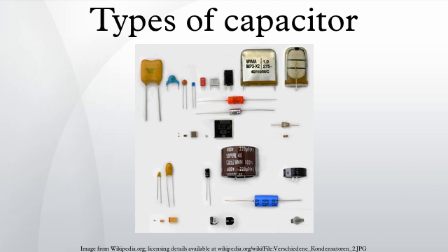The internal generated heat has to be distributed to the ambient. The temperature of the capacitor, which is established on the balance between heat produced and distributed, shall not exceed the capacitor's maximum specified temperature. Hence, the ESR or dissipation factor is a mark for the maximum power a capacitor is specified for.